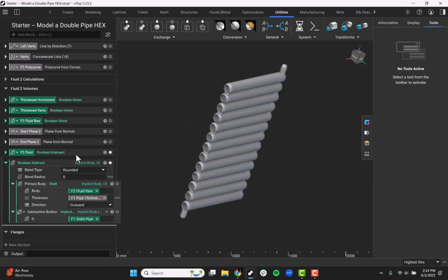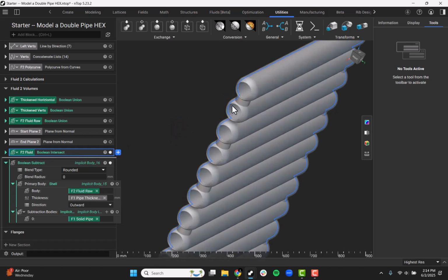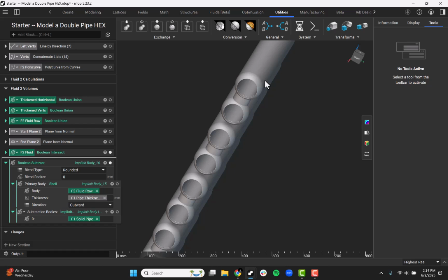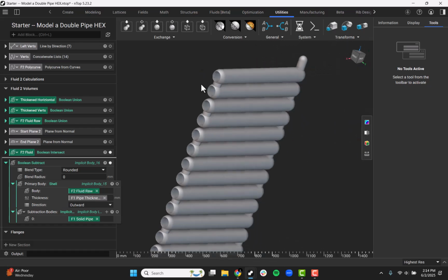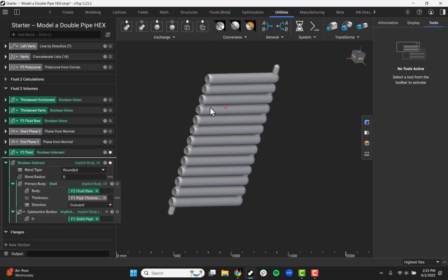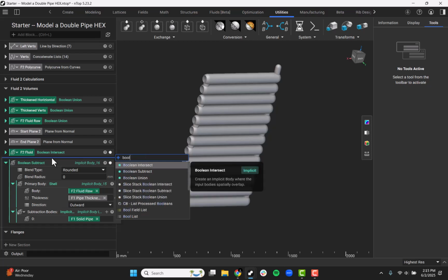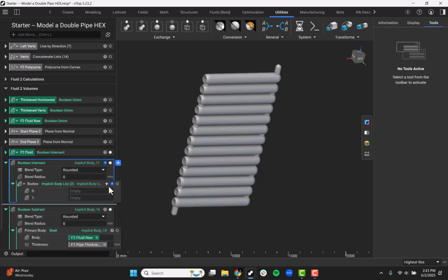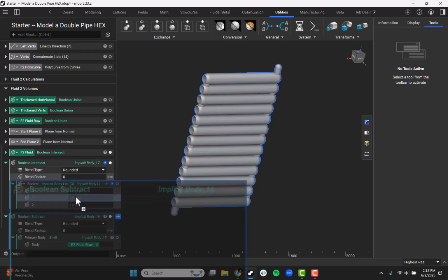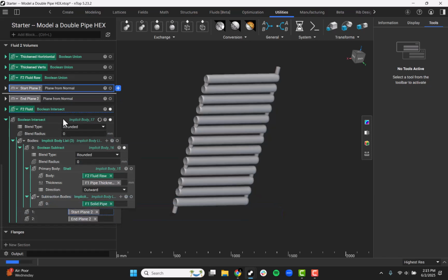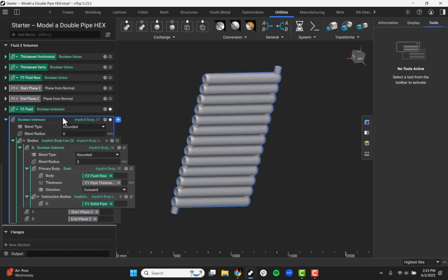But if I want to show off what my second fluid looks like, if I look inside, I can see that our fluid is not going to penetrate that region. To finish off our final fluid 2 pipe, I'm going to trim off those 2 sides here. So I'll do another Boolean intersect with this and those 2 planes. And this is going to be our fluid 2 pipe.